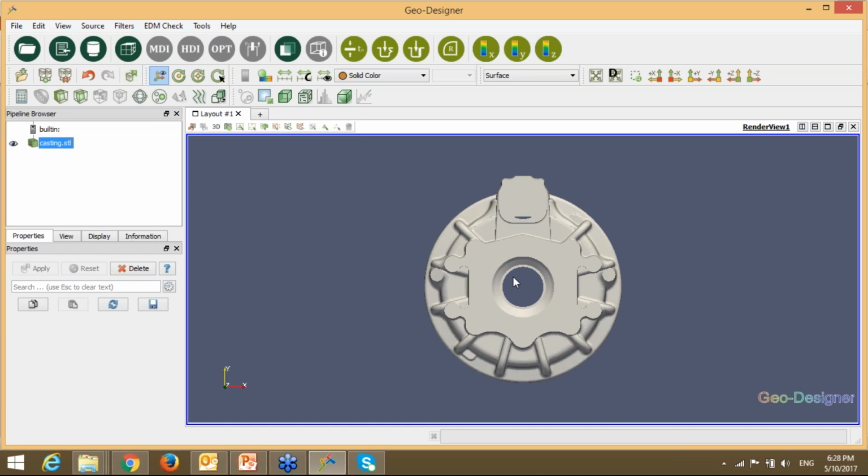The reason is that when you do reverse engineering of an existing casting part or gating system design, you have already invested in your pattern. You already have your tool and pattern available, which is difficult to change, say the location of your riser or neck size, or the location of the sleeve, or the location of the inlet or feeder. So it is very difficult to change once you make a pattern. These things are very costly and difficult. Here we can do this upfront, which could save lots of cost later on.